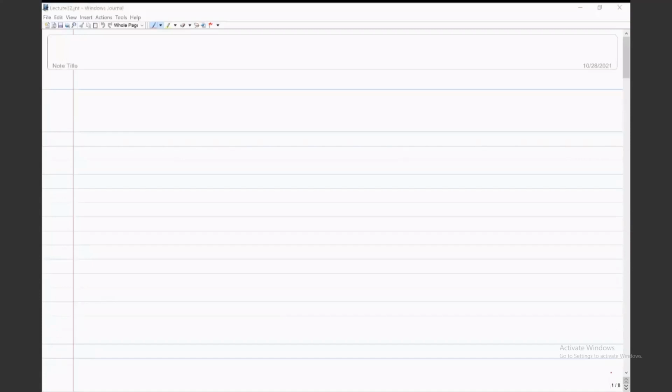Suppose some point load is given at a node. If there is a point loading, then the difference of Q1 and Q2 would be equal to that point load. So that will come as it is. I had discussed that earlier. For the elastic rod under axial load, the same concepts apply, which I had discussed, I think even in the dynamics problem also. So it is done in a similar manner. Even though the formulation is in the undeformed configuration, it still works in the same manner. Yeah, right. Okay.